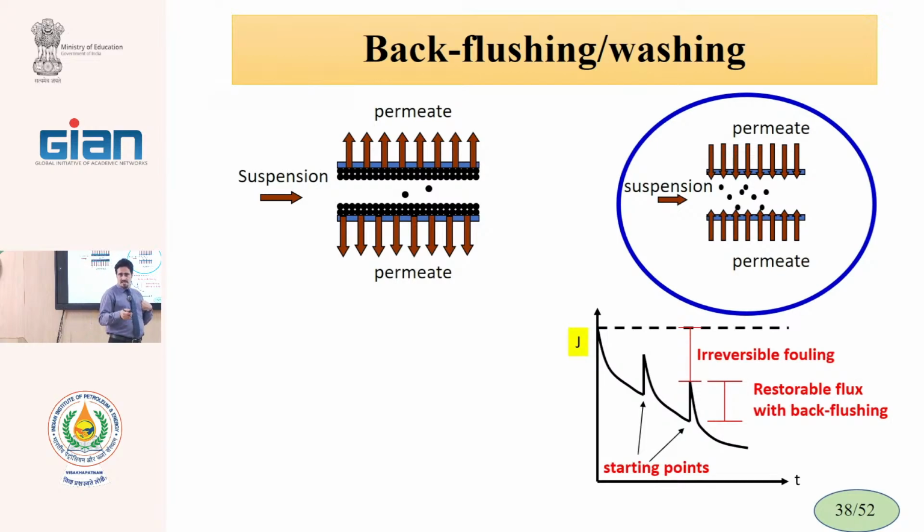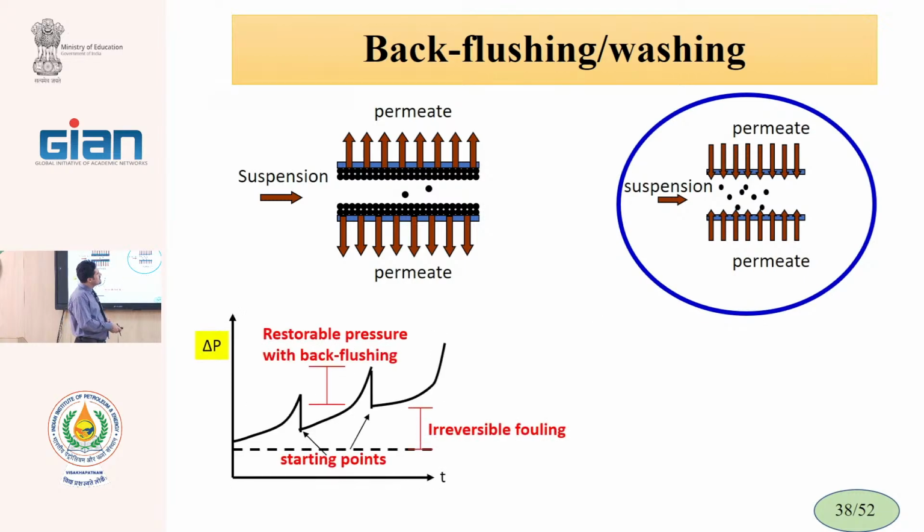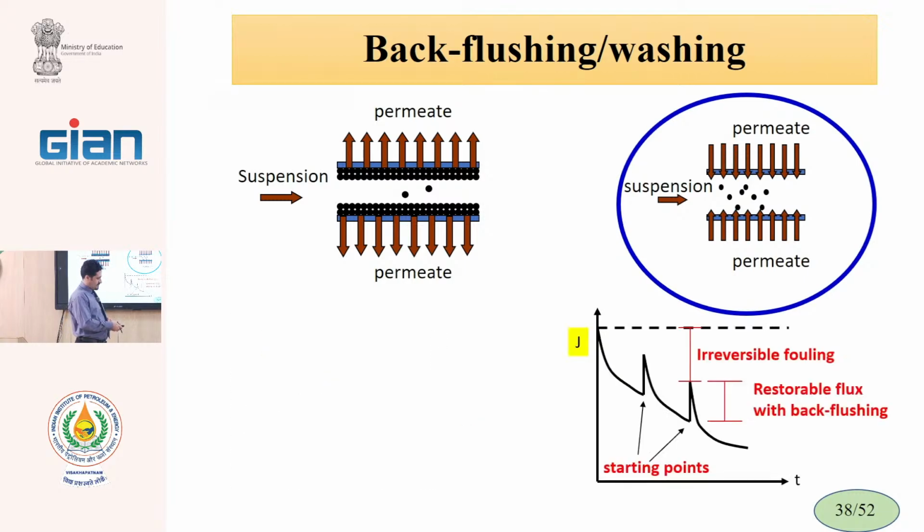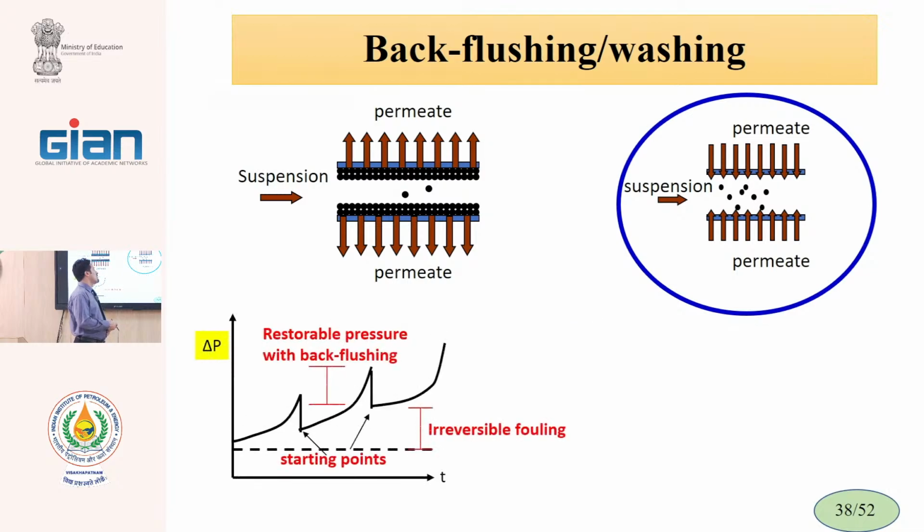And after 5-6 times for RO membranes, or 1,000 times for UF membranes, the recovery of the flux is very low, and we must change the membranes. This diagram is for flux, and this diagram is based on pressure. In industry, we want to produce a product, and the product capacity should be constant, okay?